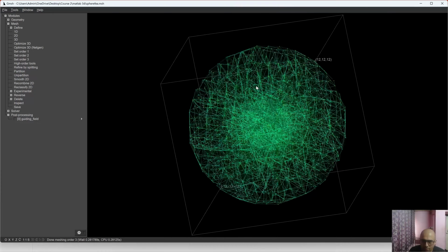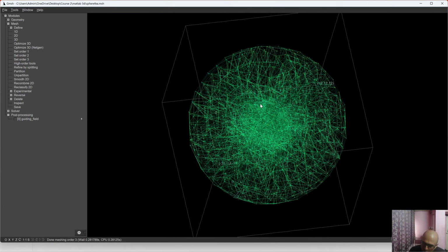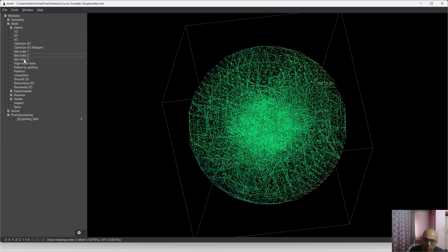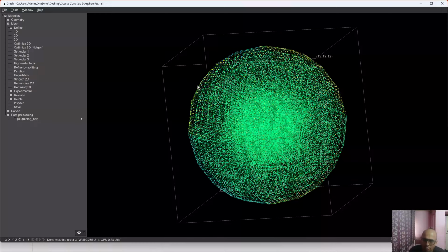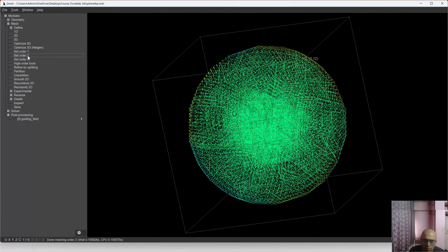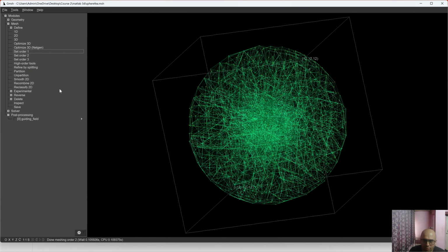Each tetrahedron will have shape functions or polynomials, which are basically 3D polynomials, and you could add more polynomials, and for doing this you increase the order. So this is done by adding more points onto each tetrahedron. You don't increase the number of tetrahedrons, but you just add more points. Okay, so you're just increasing the number of points, but not increasing the number of the tetrahedrons.